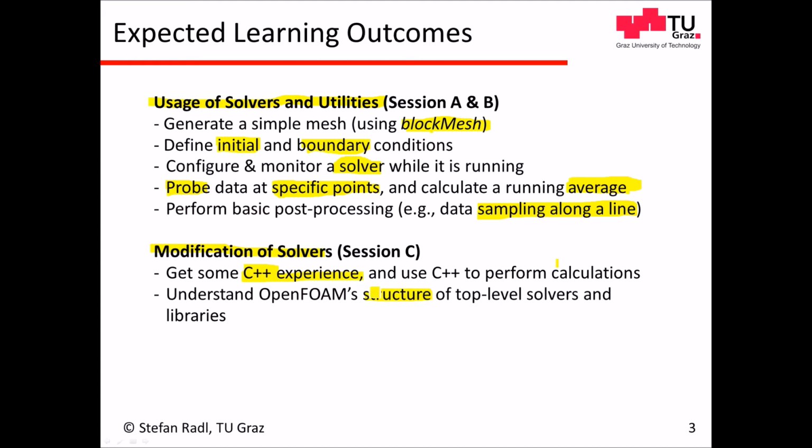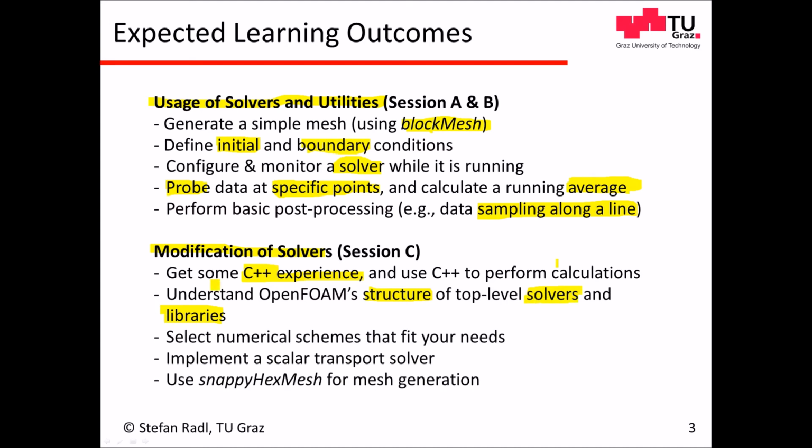You will see that this mainly consists of libraries. So the libraries provide very basic functionality, and this functionality is then harnessed in solvers that then are designed to solve a specific problem. In this session C, we will also look at numerical schemes, how to choose them. Then we will do a programming example implementing a scalar transport solver in OpenFOAM. And finally, we'll use this snappyHexMesh tool. You see it is also a meshing tool, but focuses on much more complex geometries and more advanced topics.